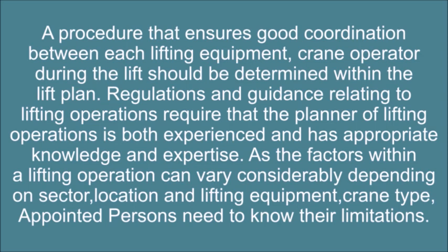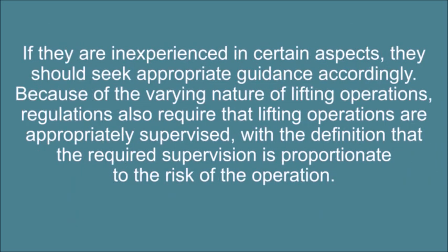Regulations and guidance relating to lifting operations require that the planner of lifting operations is both experienced and has appropriate knowledge and expertise. As the factors within a lifting operation can vary considerably depending on sector, location, and lifting equipment, crane type, appointed persons need to know their limitations. If they are inexperienced in certain aspects, they should seek appropriate guidance accordingly. Because of the varying nature of lifting operations, regulations also require that lifting operations are appropriately supervised, with the definition that the required supervision is proportionate to the risk of the operation.